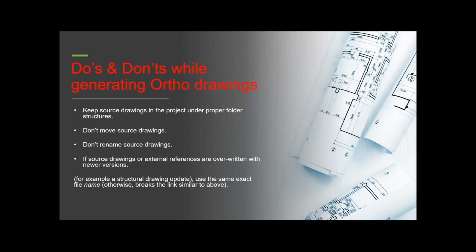Again, on the don't side, do not move source drawings. Do not rename your source drawings. Source drawings means your model drawings. If you are trying to rename, you have to do it in your project browser, and then you also have to create your new ortho drawing. Don't do that in Windows Explorer and expect the connectivity with your ortho drawings to be done automatically.